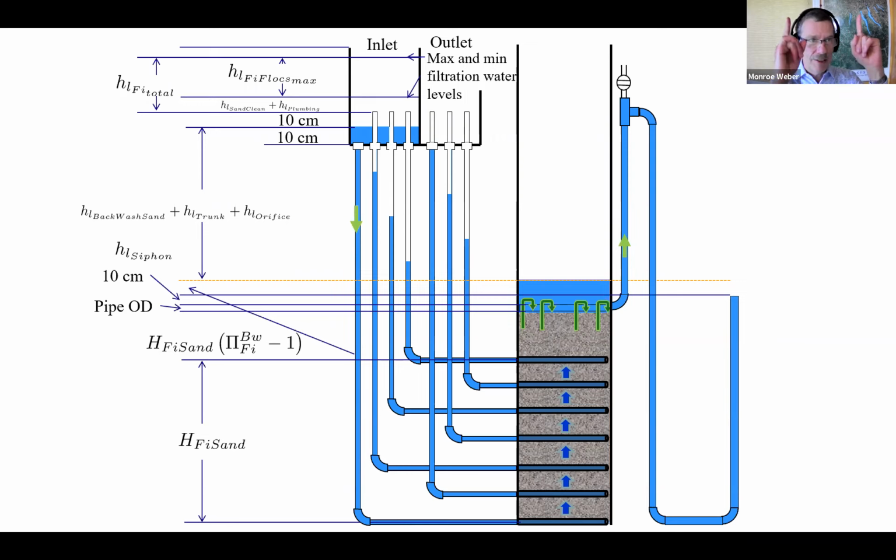And so there is water above the sand that was just used to backwash the filter. If you haven't run water for a very long time during backwash, there is still a higher concentration of turbidity or particles in the water above the filter when you finish backwash.